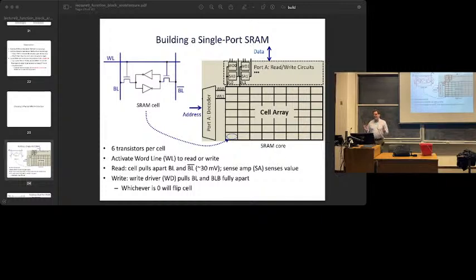So they're quite capacitive. So to make the SRAM read relatively fast, we don't wait for one of these bit lines to get pulled all the way to 0 and the other one to get pulled all the way to 1 during a read. We just let them get pulled a little bit, maybe 30 millivolts. So this might be pulled down after some amount of time to 30 millivolts lower, and this one might be pulled up. Actually, it doesn't get pulled up very much. The pull-ups are weaker, so maybe it gets pulled up 10 millivolts. So a voltage difference develops, and then the RAM basically activates sense amps.